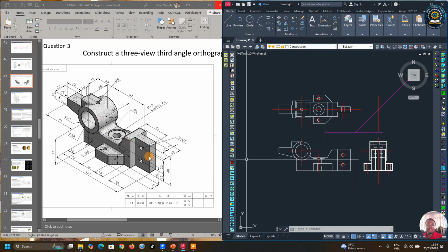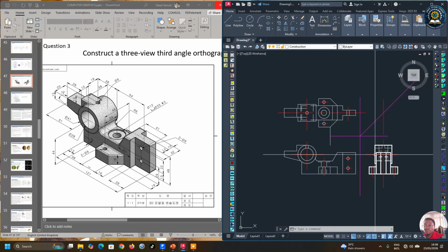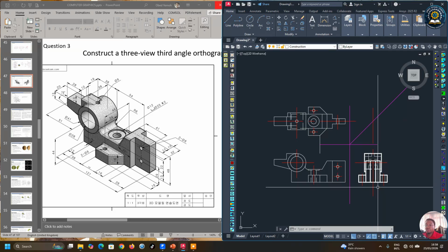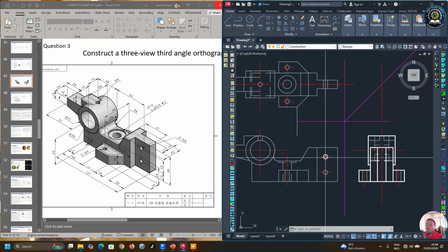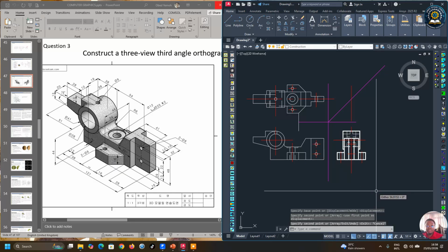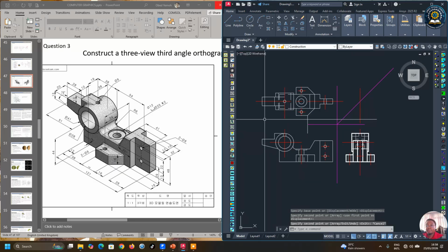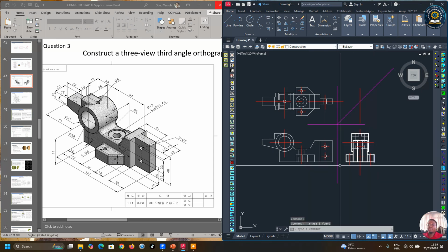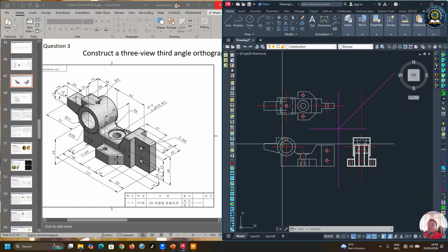If you go, use a pen and pencil and sketch out the end view. When you sketch out the end view, compare it to the video when I send it to you and see if we've done the right thing or not. Bear in mind that we are supposed to even show this one inside this as hidden details. So what I'm just going to do is just put the center lines in them, and in conventional representation, they will mean the same thing, center holes. So put the center lines in them like that. So we have our plan, our front, our end view.